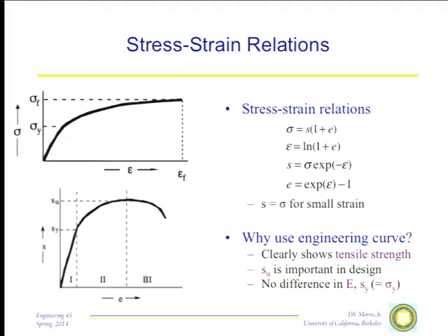From the true stress strain curve, it's actually very difficult. I can extract that information, and I'll tell you later how to do it. But it's really difficult to get it, and I need a completely new analysis in order to extract that information. So from the point of view of the engineer who cares about the modulus, the yield strength, and the ultimate breaking load of a specimen that has a pre-specified geometry, the engineering stress strain curve contains the information that you need to use. So that's why we use that.